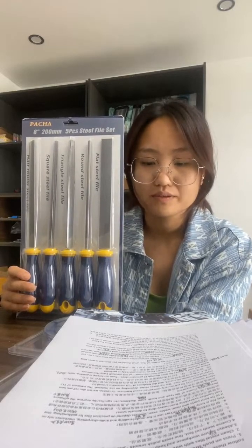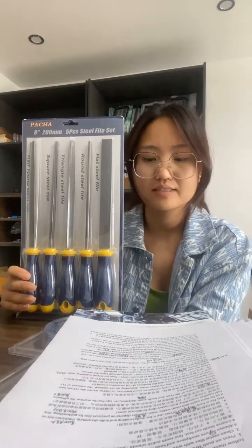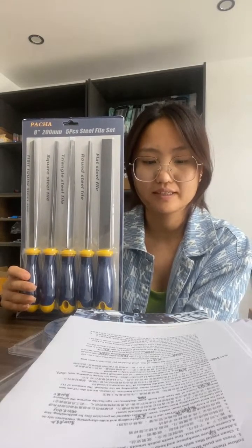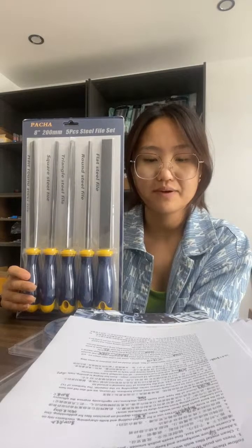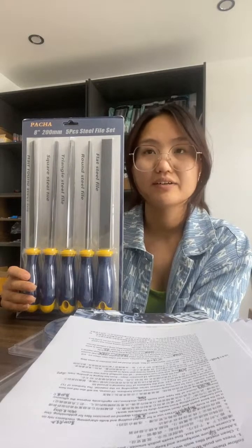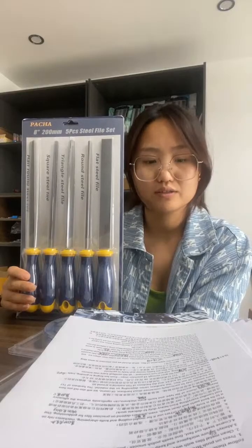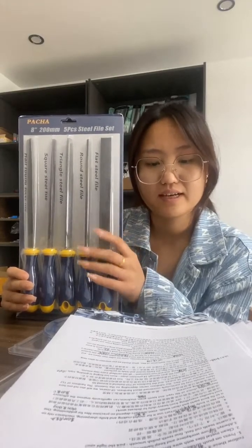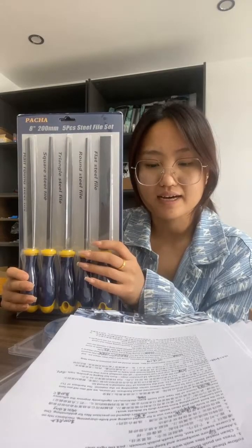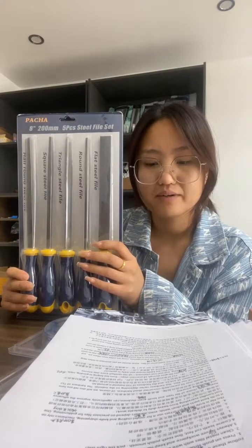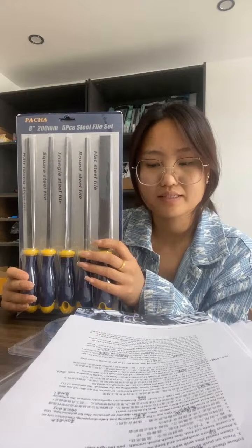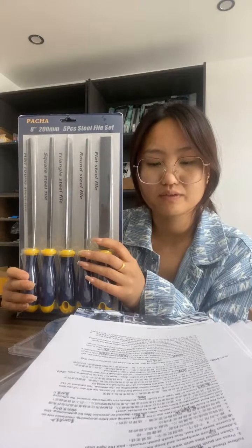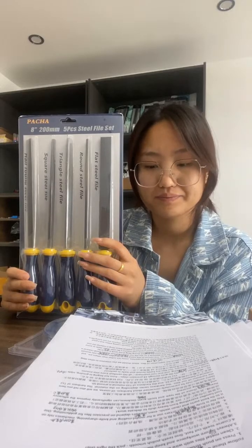For instance, a soft ductile metal requires a neat file, and only light pressure must be applied during filing if the work is not to be deformed. Conversely, a hard and less ductile metal may require a file with duller teeth to avoid them biting too deep and breaking off when pressure is applied.